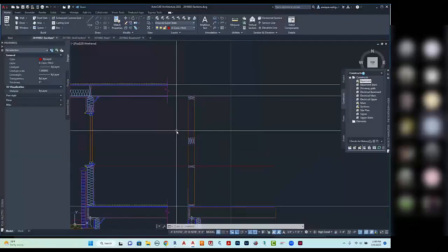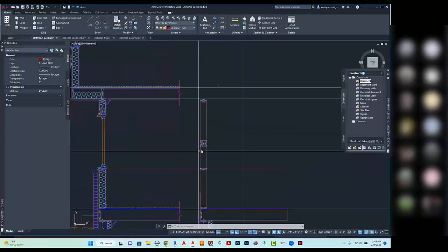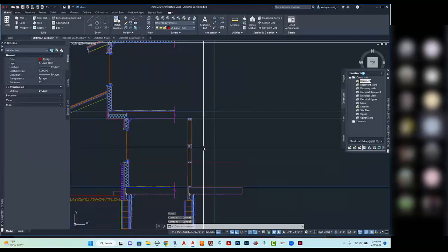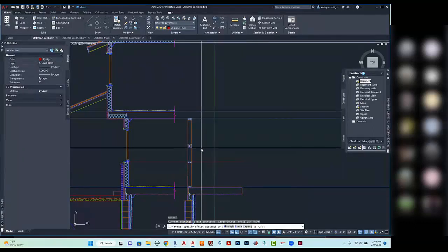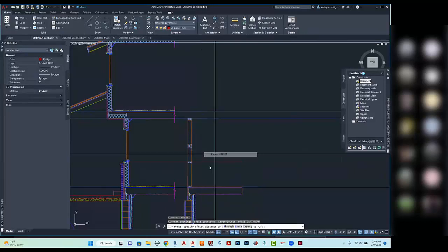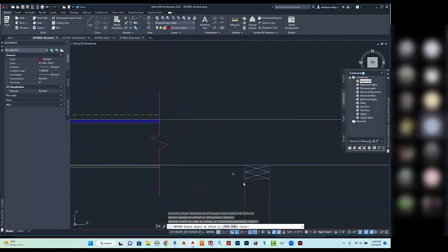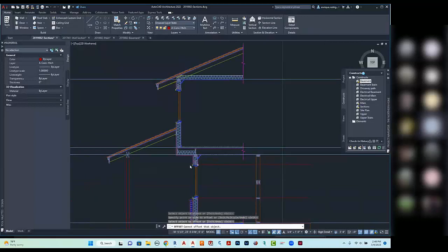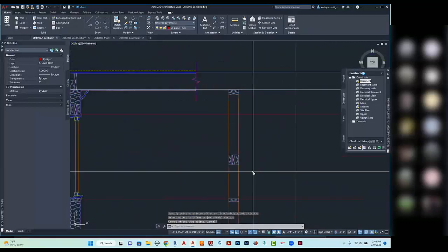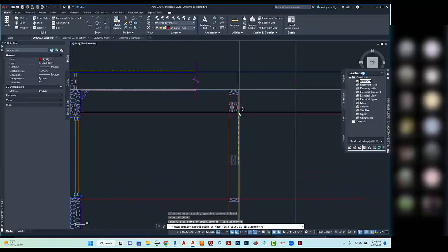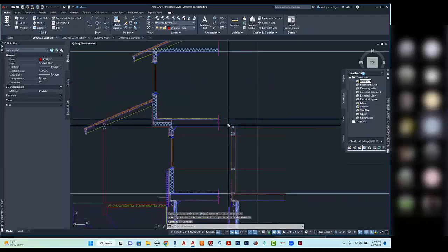Looks like it right here. We were setting up the header. I'm going to go ahead and assume that you probably had a 3-foot by 4-foot or a 4-foot by 4-foot. I'm going to go ahead and offset 4 feet, line up in here, which means that my header is going to be about up at this location, which is where they put it. I'm going to go ahead and move my header up to that location right there.